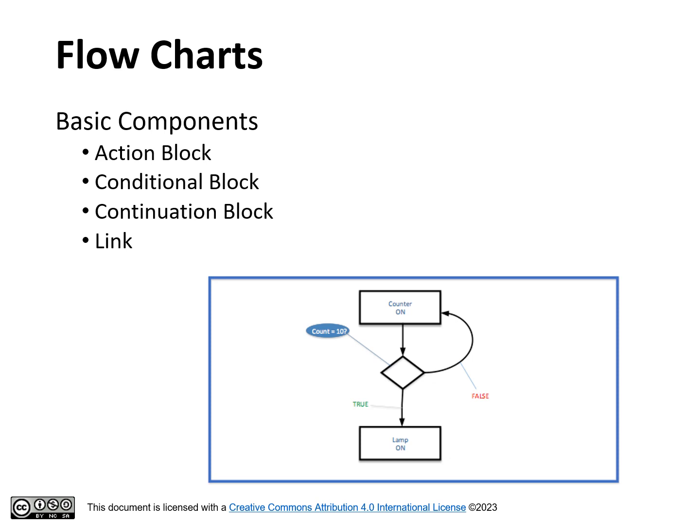A simple control logic program is shown in the figure. The control logic implements a system requirement of flipping the switch 10 times before the lamp turns on. A counter with an accumulator keeps track of the number of times the switch is flipped. When the accumulator reaches 10, the lamp is energized.